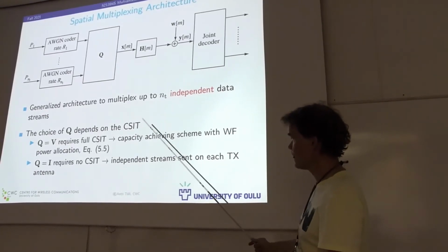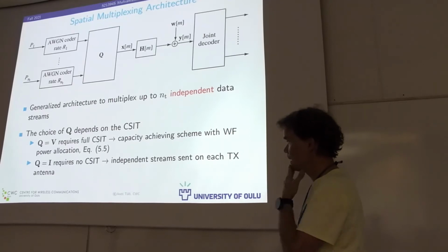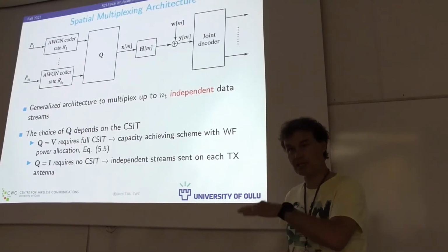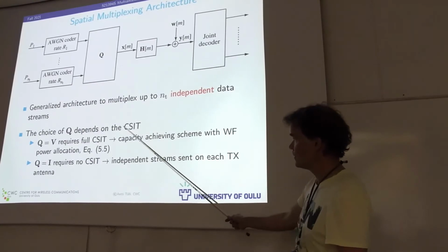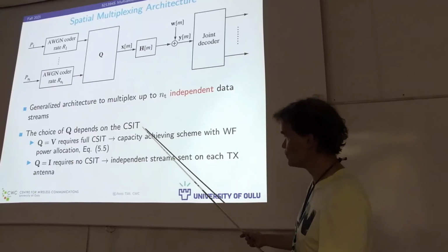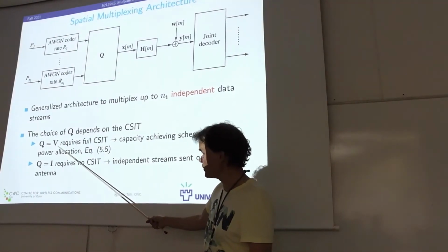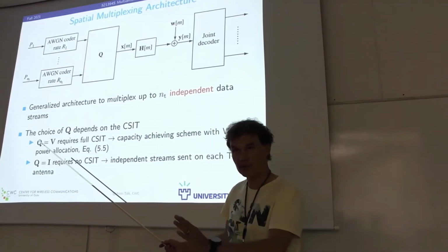So ideally, if we have sufficiently high SNR for the pilot estimation, so that the estimation noise can be ignored, you can fairly safely choose your precoder to correspond to the right singular vectors of the channel matrix that you have estimated.